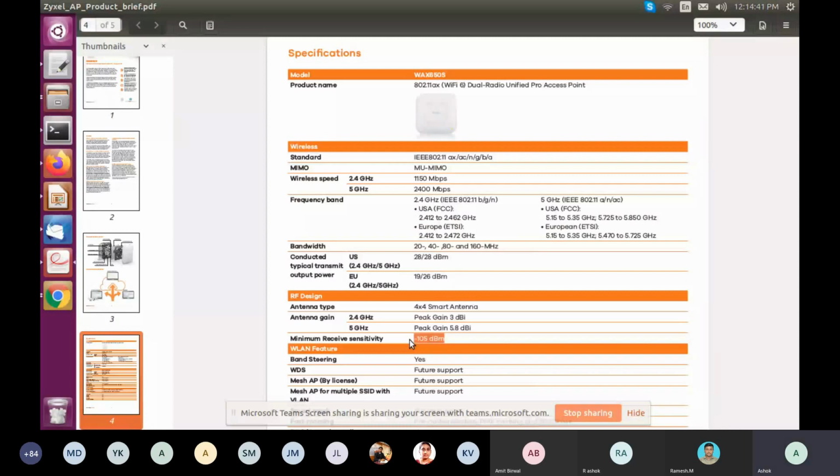Because you've taken this, you have an idea of what is meant by free space path loss, then you plug in these numbers and see the rate and the range, meaning the range at which it starts failing. You can assume your fading margin to be 20 dB or 30 dB or 40 dB or whatever it is, and you can find out at what distance it starts failing. For a given link availability, you can use these numbers and do it.